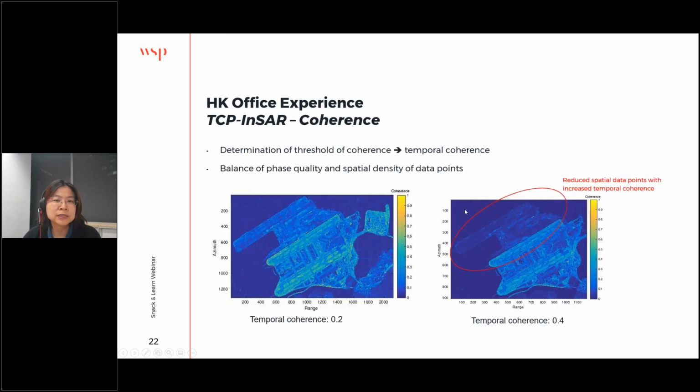We also have these coherence estimators. In the past we may not have known how coherent the pair of images is, and how many coherent points we can find. Let's say a coherence of 1 is perfect, which means the point can be detected in every image. But unfortunately, as I mentioned, because the ground is under development, for stable ground the coherence is always consistent, but for development grounds with subsequent constructions or buildings, the coherence is lower. So it depends on what the user needs.